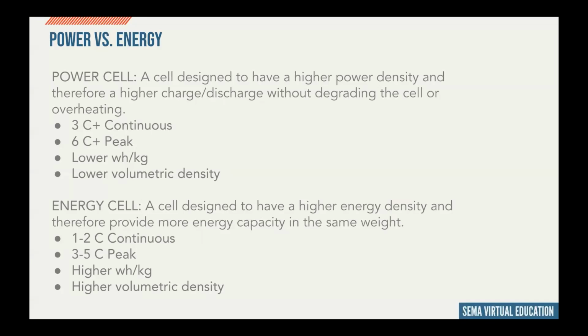At larger capacities, they do have enough current discharge for higher performance applications. We'll get into some of the calculations later, because one of the core fundamental elements of designing a battery pack is identifying the cell to be used and doing all the calculations so that you know how many cells are in the series and parallel configuration.